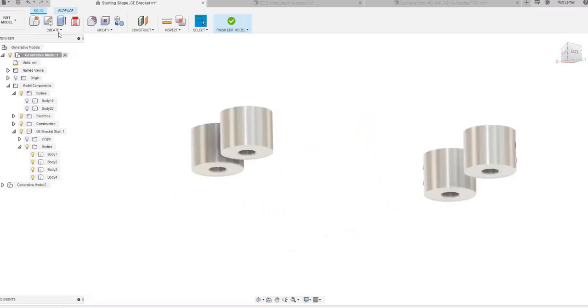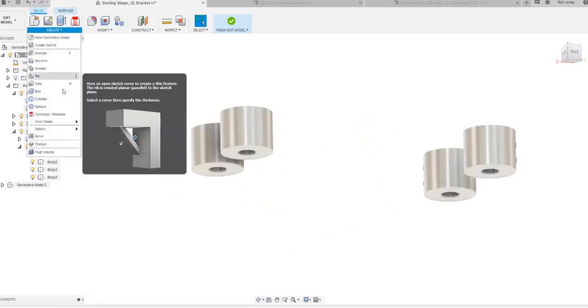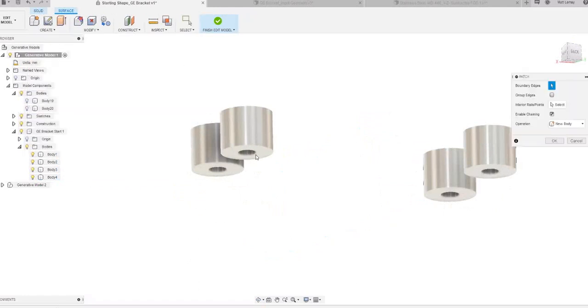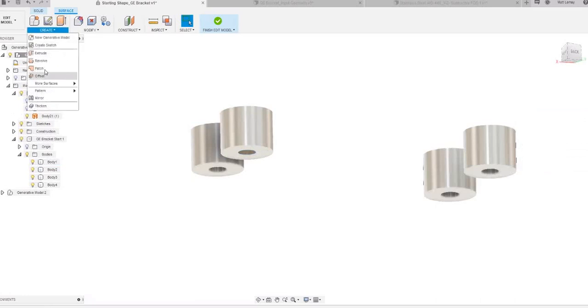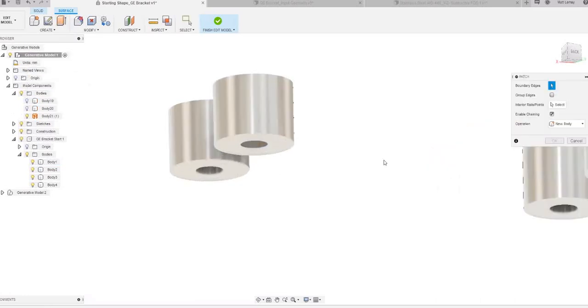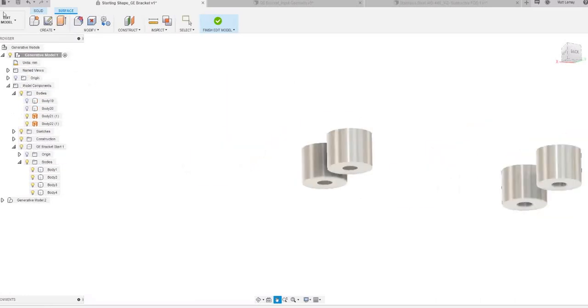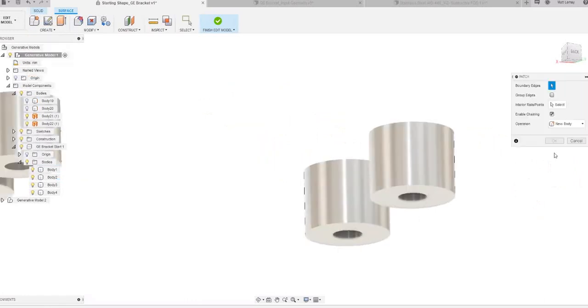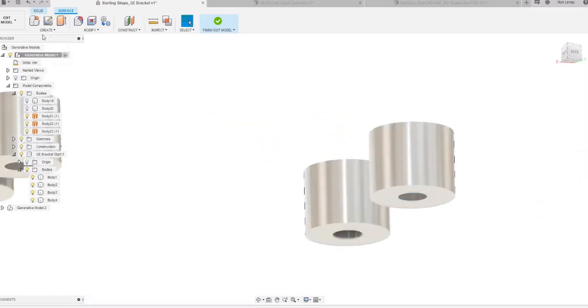And then we also want to make sure that we have enough clearance within our assembly to actually reach that later on. So what I would do, and this is just one way to do this, is I might patch each one of the surfaces. Again, this is using some surfacing tools within Fusion, creating a patch on each one of those faces.